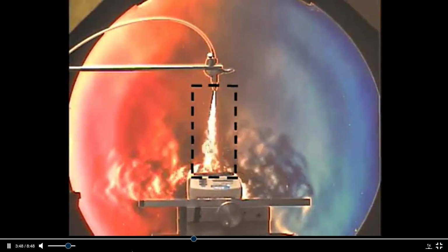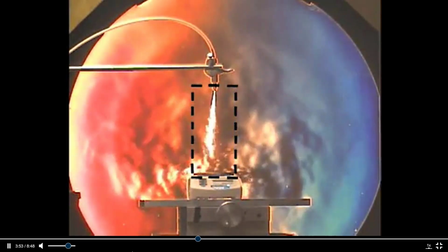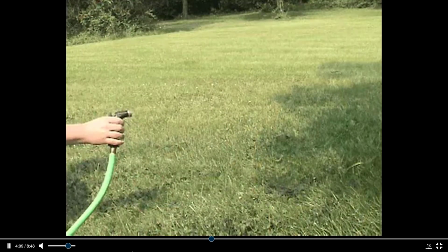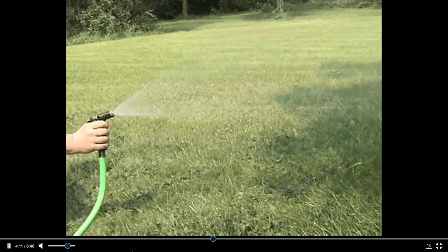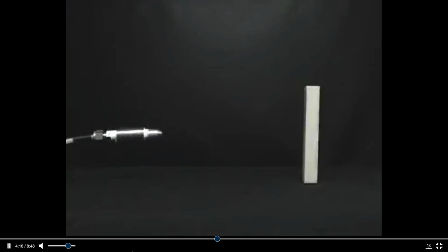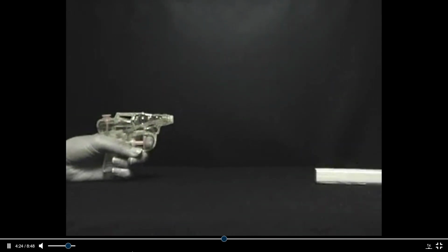Here's an appropriate control volume to analyze this process. A sum of the forces and the momentum fluxes in the vertical direction using the Reynolds transport theorem and Newton's second law of motion reveals that the reaction force measured by the scale is simply equal to the momentum flux coming out of the nozzle. The momentum flux of a fluid is the product of its velocity and mass flow rate. Thus, we can get about the same momentum from a high-speed jet of a light fluid like air as from a slower jet of a dense fluid like water.